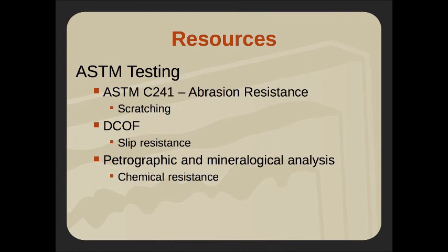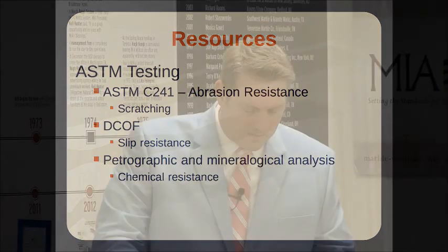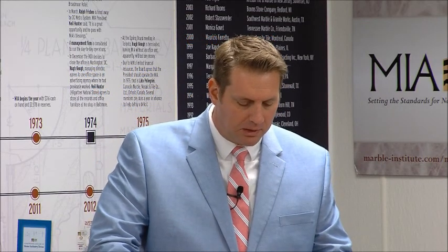Moving on, these are less structural and more performance-related ASTM tests here. The C241 is our abrasion resistance, and this is really going to tell us whether or not it's got any sort of ability to withstand scratching. I'm not going to put a marble or a limestone down on a large commercial project floor that isn't hitting our minimum requirements for the C241, because it's going to be a mess after just a few weeks of the mall being open. It'll be scratched and torn up. So that's important that we've done that homework.